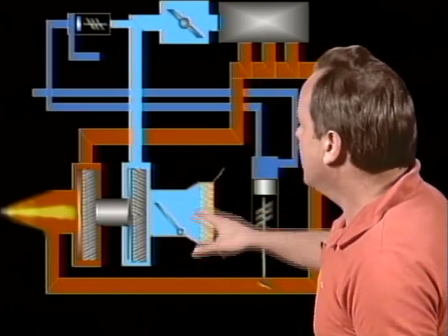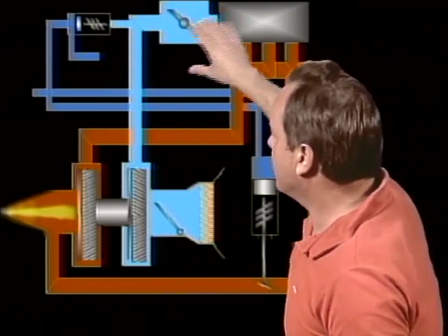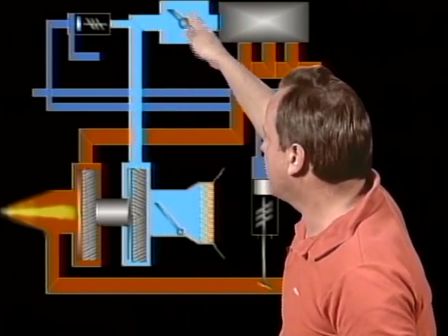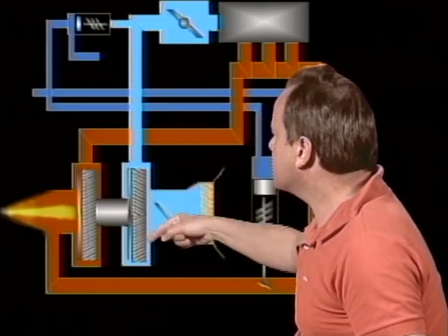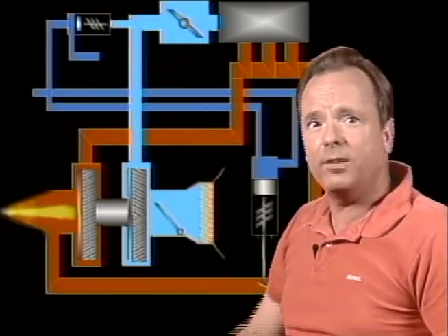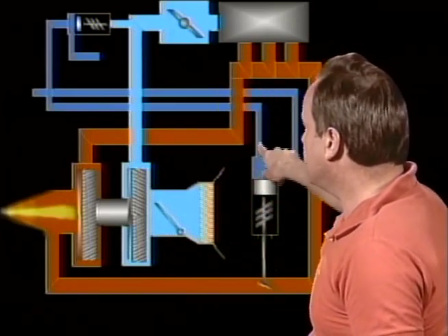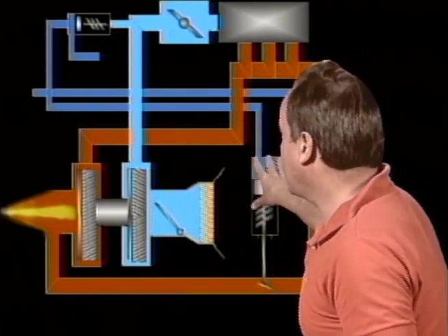You have an absolute pressure controller, and what it does is it says, look, we'll say 29 inches of manifold pressure on this airplane at all times before it gets to the throttle valve, the upper deck. So we're going to have 29 inches of manifold pressure before you get to the throttle valve all the time, and we're going to run this compressor hard enough to always maintain, we'll say, 29 inches manifold pressure. That's called the absolute pressure controller, and it does the same thing. It either bleeds or does not bleed oil pressure off the wastegate controller, off the wastegate actuator there.